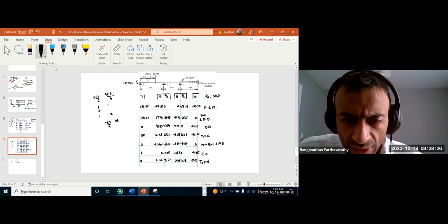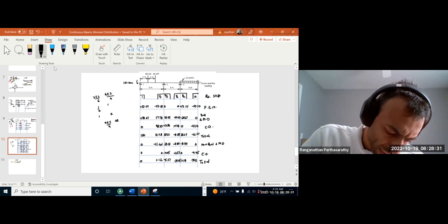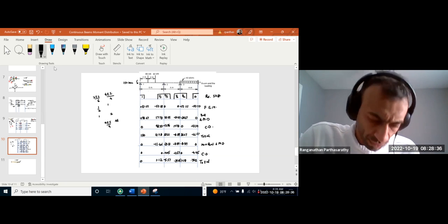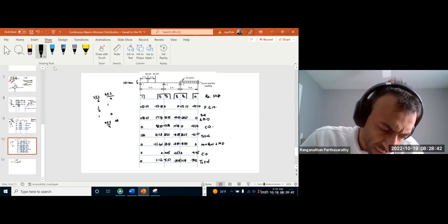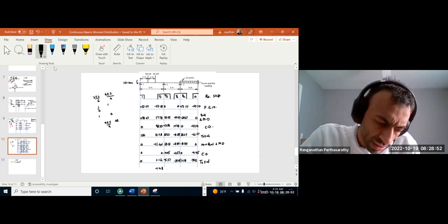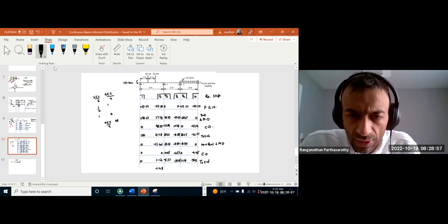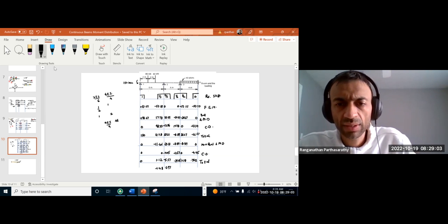Okay, so now you can see we have much smaller moments to balance. Negative 5.57, positive 1.12, negative 4.45. So put 1/3 of that to this side. So we have negative 1.48 on this side, 2.96, negative 2.97 something.